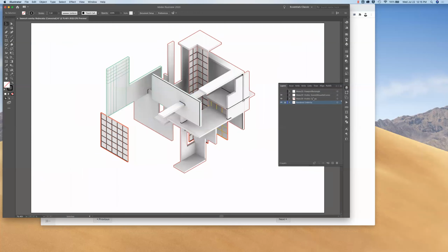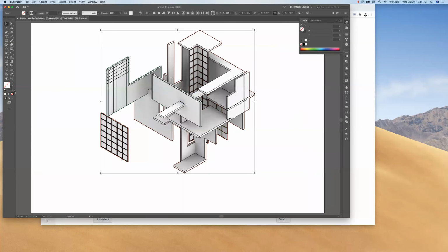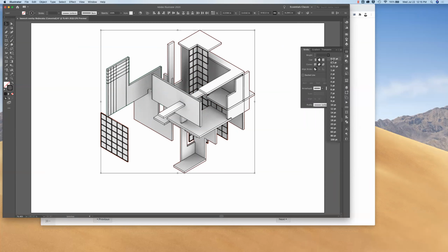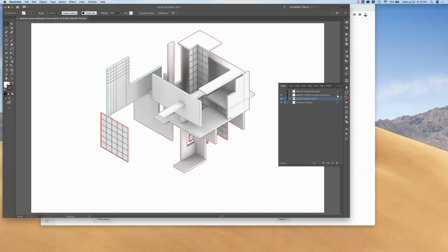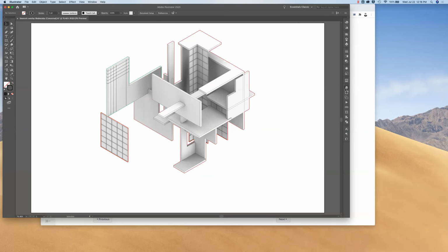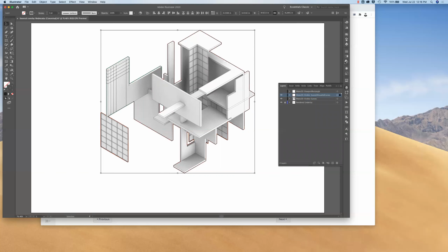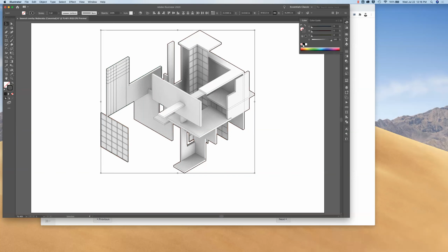And I'm going to take the visible curves, and I'm just going to select those, and I'm going to turn those to black lines. And I'm going to change the stroke weight to something like 0.25, something like that. Okay. I'll do the same with the scene silhouette curves. You know, it's up to you what you do here. So not only am I going to change the line weight, the stroke weight, I'm going to change their color again to black. That would help.